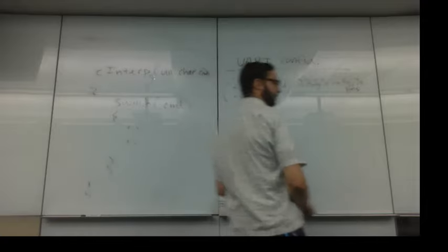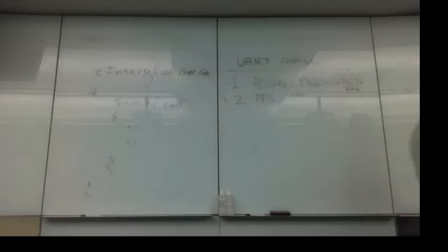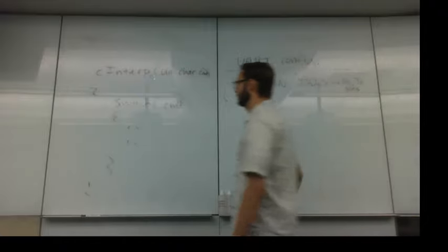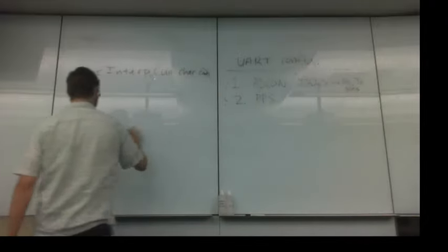So these two steps here are kind of related. You have to check the peripheral pin select, and there's a nice table in the data sheet that shows you which pins you can use for peripherals. And then you write to the peripheral pin select register and basically connect those to the PIC.